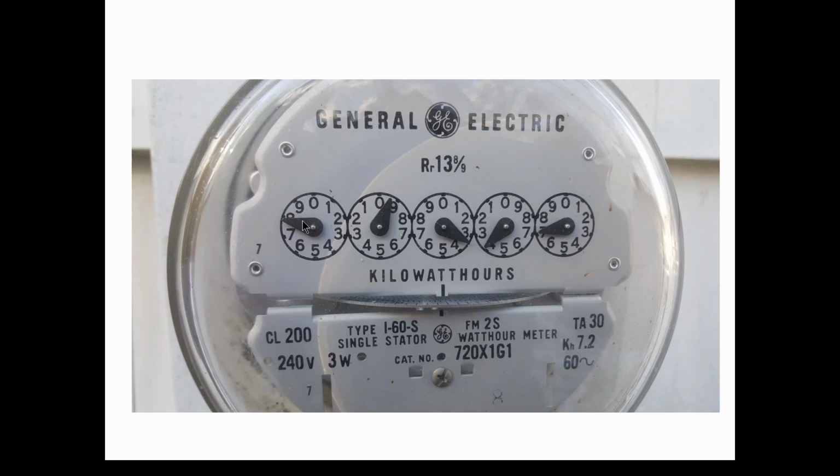So let's start on the left-hand side. You can start on either side. But you can see that this first dial goes 0, 1, 2, 3, 4, 5, 6, 7, 8, 9, and back to 0, all right? So this first reading is more than 7, but it hasn't quite reached 8. So what you do is you write down 7. So this dial is reading 7 because it hasn't gotten to 8 yet. This next one goes in the opposite direction, counterclockwise. 0, 1, 2, 3, 4, 5, 6, 7, 8, 9. It's over 9, so we'll call it 9, all right?